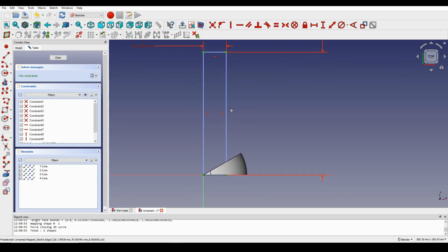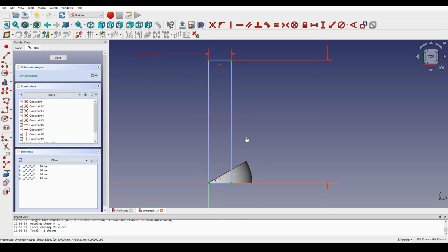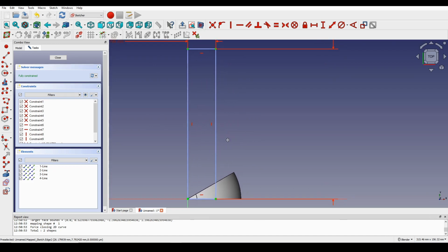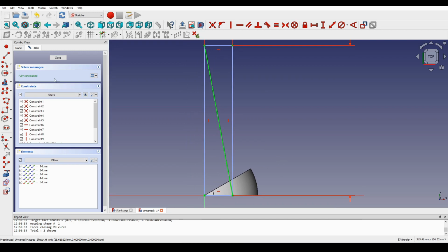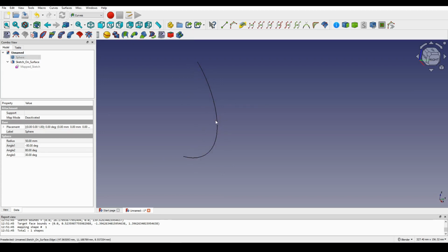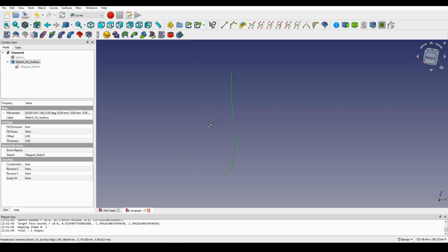Okay, so I also view the section, see through, and I don't have to draw a sine curve. I just draw a straight line connecting from the top left to the bottom right like this, and I close that, and you can see I will hide the sphere. You can see we have a sinker like this, right?